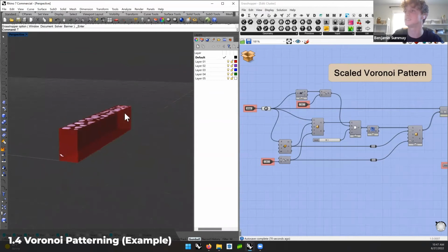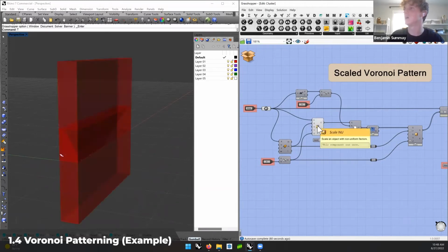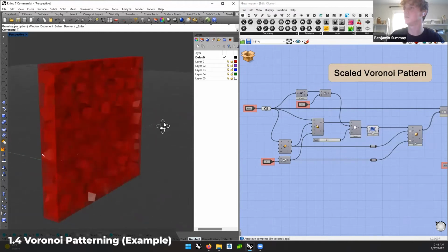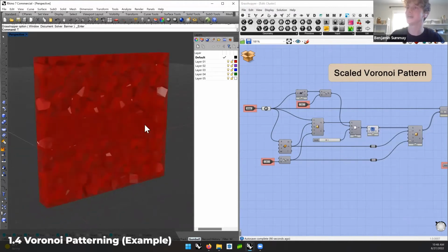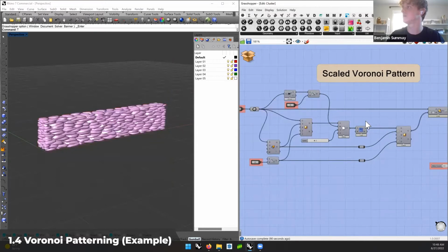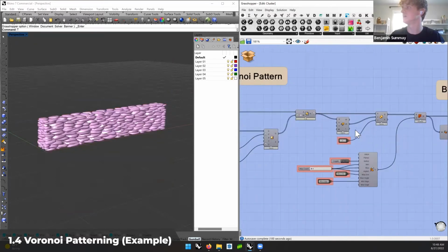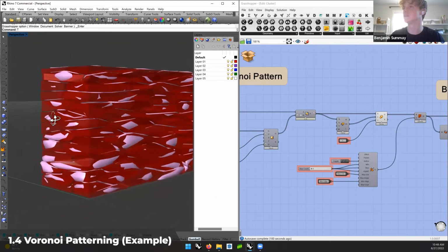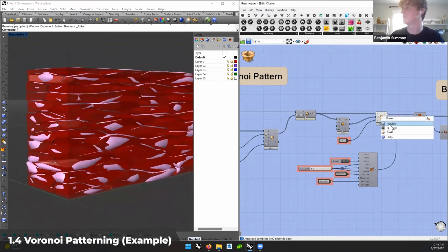In order to create the stacked wall effect, we're taking the wall itself and extending it higher and longer and below in order to create the Voronoi pattern, which can then be smushed down to create the stacked stone effect that we're looking at the tail end of the script. I'll jump through this a little bit, and you can see that we're scaling them back a little bit so that we have a bit of a cushion in between the different stones and the Voronoi pattern.